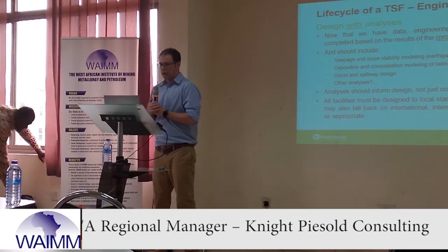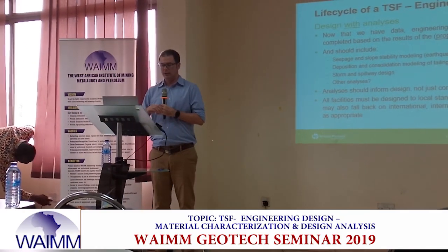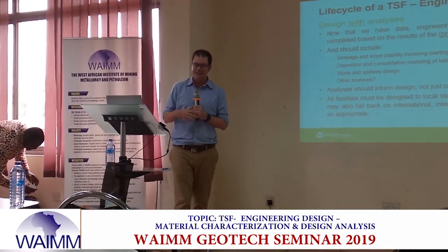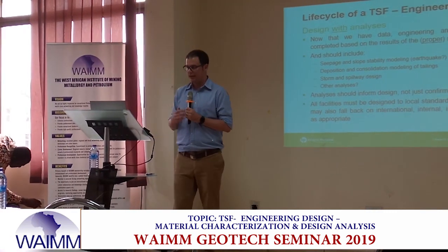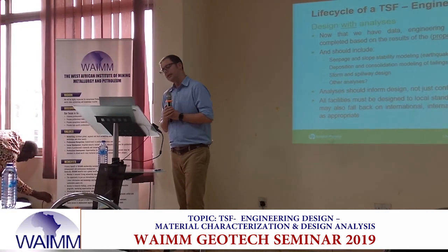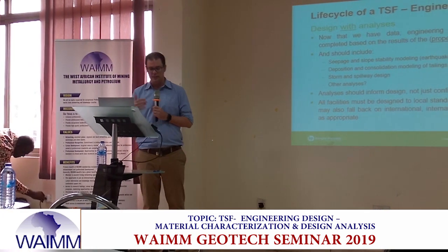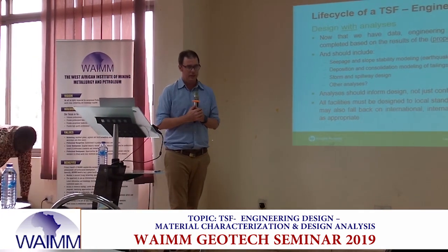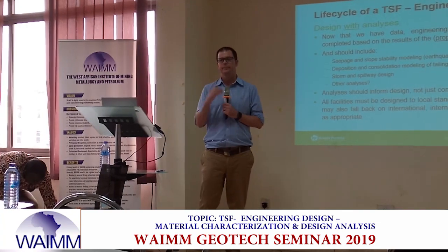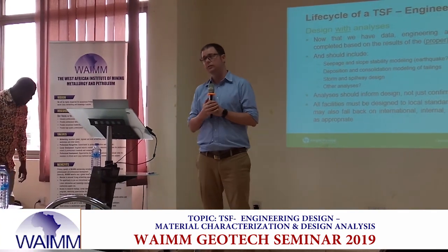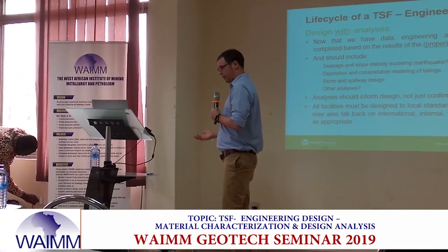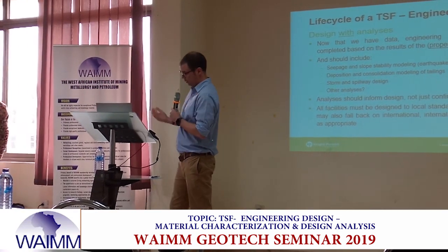So, now that we have the data, engineering analyses must be completed based on the results of proper site investigations and testing. What we need to look at is, as Dr. Akayuli mentioned, seepage stability modeling. Do we need to consider earthquake loading? The answer is yes. More so in some areas of the world and less so in places like West Africa.